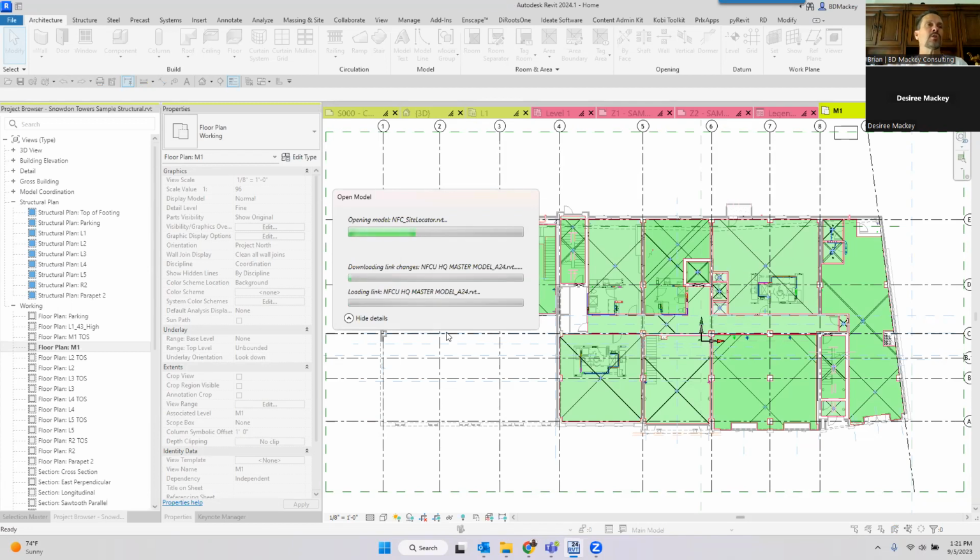So when I set that up, I do the mean sea level, then I have one for each building elevation. The CAD file I bring in at sea level, because if I am working with a civil engineer, usually everything's at the sea level elevation, except for things like contours, etc. Once we get into those contours, then those are going to be up at the building elevation-ish, and we're going to be looking at the other tools. So that's how I go through and set up.